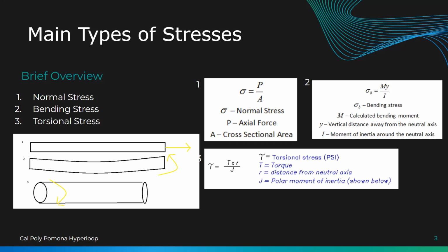So when we look at that cross-sectional area of the width or the thickness and the height, you'll have to find the center of that cross-section. And that's going to be your starting point. And from there, if you want to find this tension at the top, right here, like what I was talking about, at the very top, you see compression, and then at the very bottom, you see tension. If you want to find that, the Y value is going to be from that center, or the centroid, and then going from that to that point.